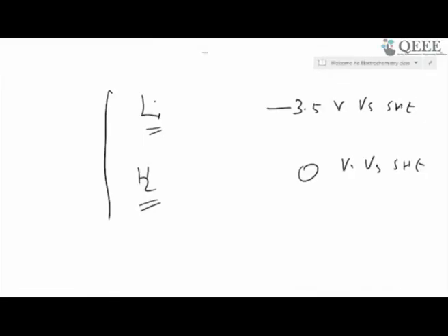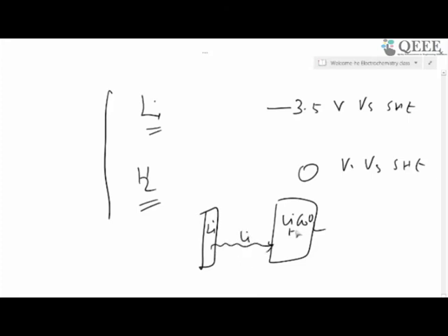So it's going to alter the state of the material. In addition to that, temperature also changes the mobility of lithium in the electrolyte because you have the lithium anode and you have a cathode LiCoO2. So when you discharge, lithium moves from the anode to cathode. That means you need to have a lithium lean matrix here. So it will move from the anode to cathode. When you charge, the lithium moves from the cathode to anode, right? So that means the movement of lithium will be enhanced with the temperature, so that may enhance the current that you get from the battery at a given overpotential.